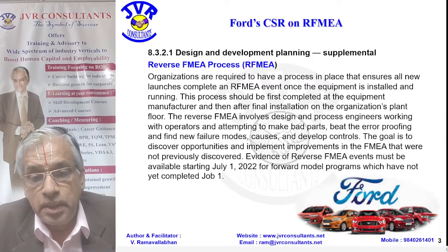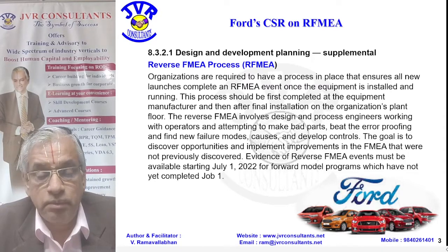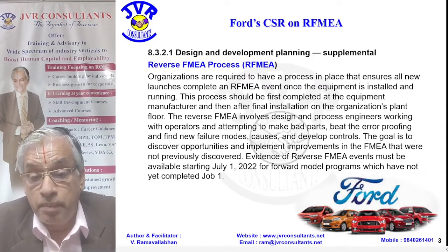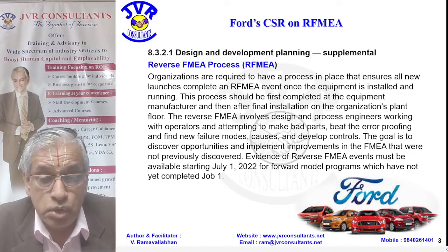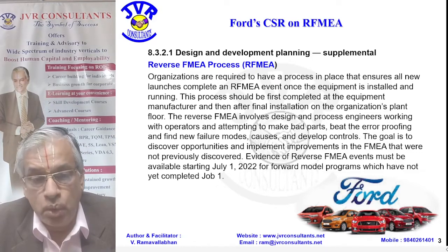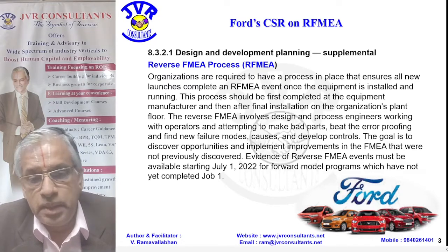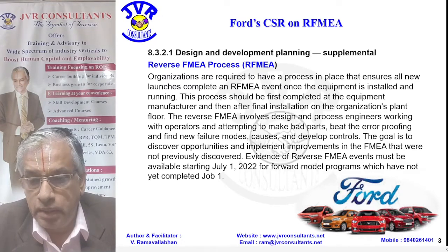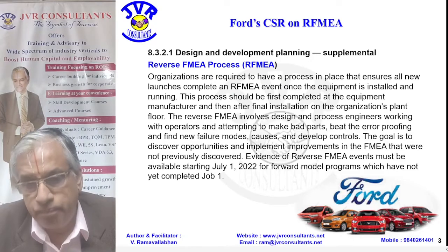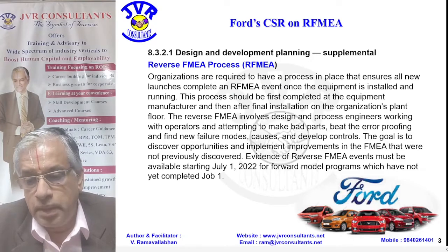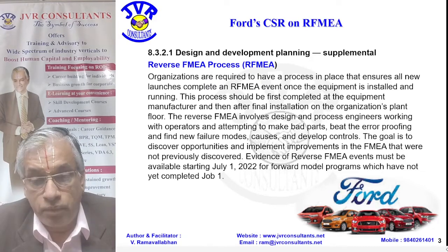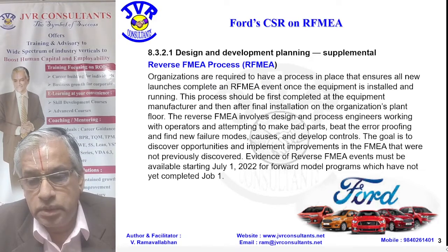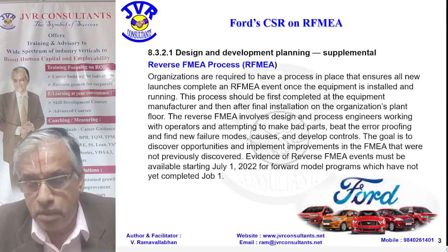The reverse FMEA involves design and process engineers working with operators and attempting to make bad parts beat the error proofing and find new failure modes, causes, and develop controls. The goal is to discover opportunities and implement improvements in the FMEA that were not previously discovered. Evidence of reverse FMEA events must be available starting July 1, 2022 for forward model programs which have not yet completed job 1.